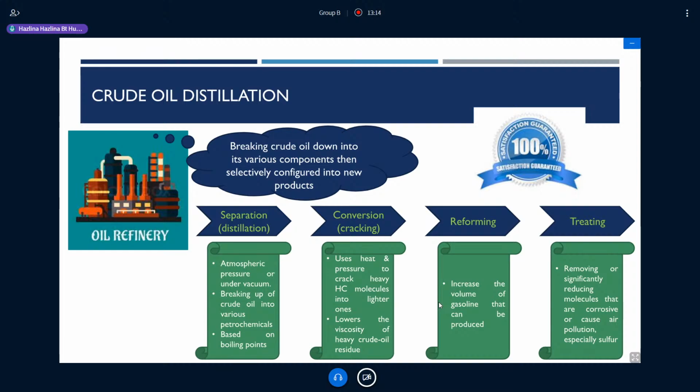Okay, after undergoing distillation, cracking, and reforming, another major process in the downstream processes is the treating or treatment process. Yeah, treatment process, you can't run away from it. Treatment process is, of course, for you to increase the purity of your expected product. That is number one. Number two is, of course, you want to remove impurities. When you remove impurities, meaning you are going to remove the sulfur content just now. Maybe you want to remove carbon dioxide content. Maybe you want to remove water, and of course, definitely you want to remove anything that is not your product, which is the hydrocarbon component. Okay.